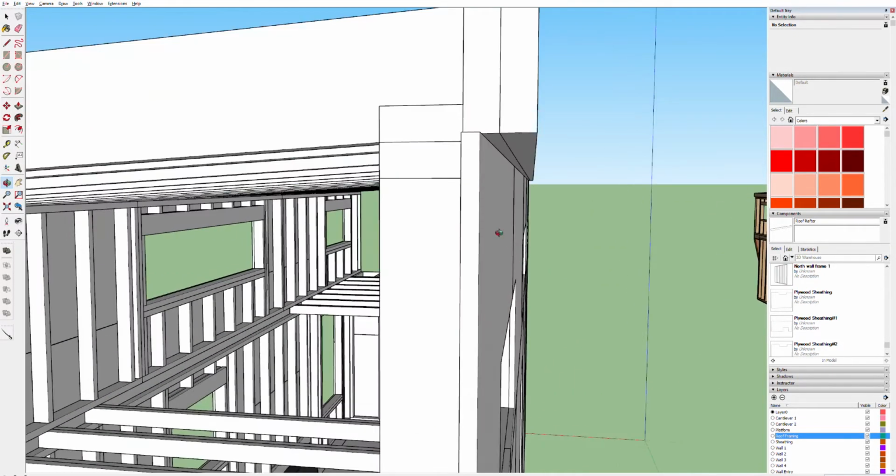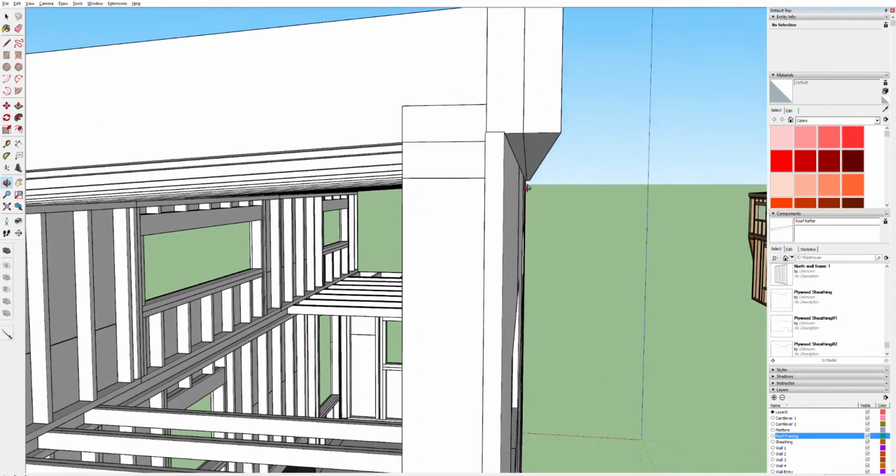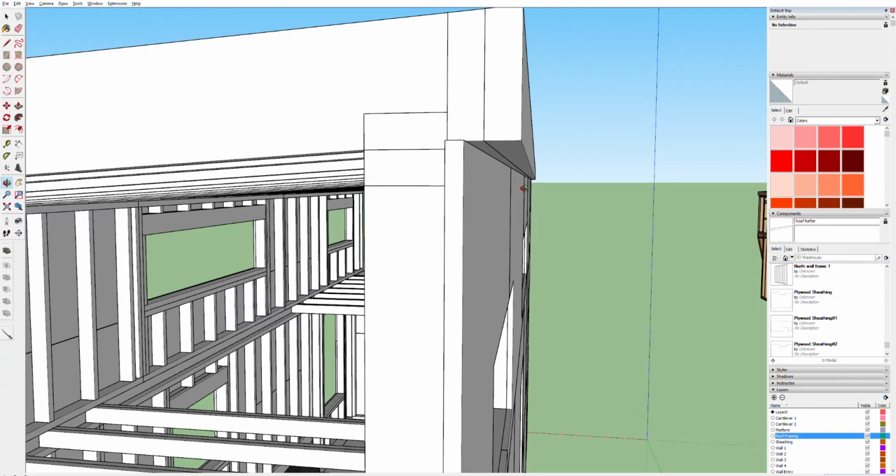So on top of the sheathing, we're going to have some board and batten. That's going to be, I think, about a quarter of an inch or half an inch thickness. I'm getting this special stuff, which I'll show you later. And then I'm putting on 3/4 inch of the batten siding. So when all is said and done, I'm going to have 3/4 inch of sheathing, maybe let's just say a half inch of boards, and then the vertical batten siding is going to be another 3/4 of an inch. So that's going to equal, what is that, 1.5 inches, 2 inches.